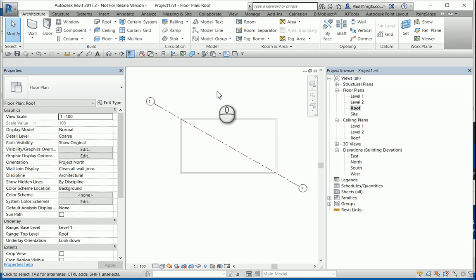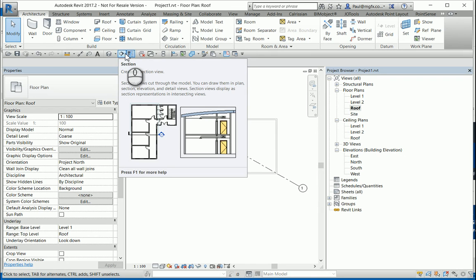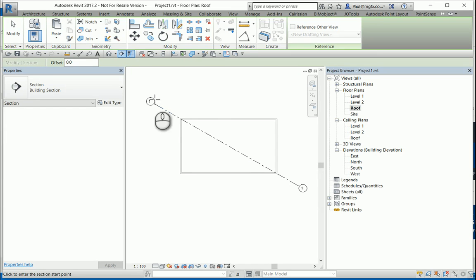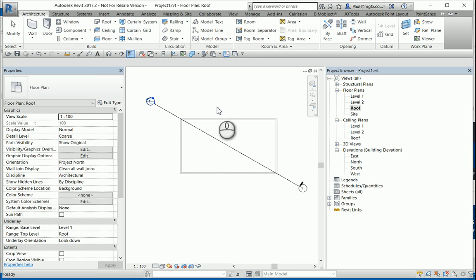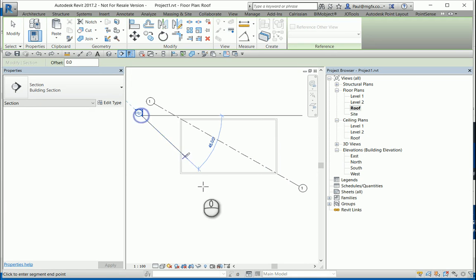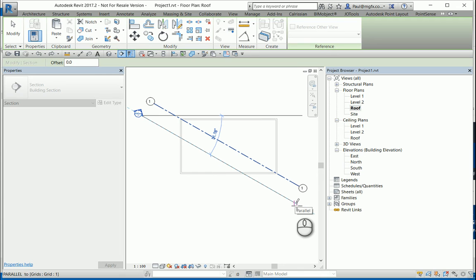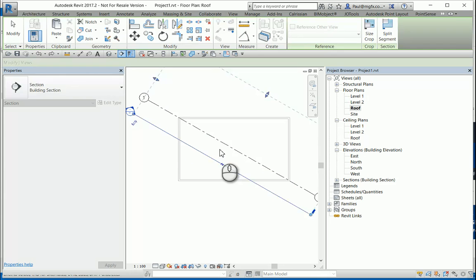Typically what one would need is a view that is normal to that plane, and you'd have to use this if you're using Revit LT. Using full Revit, we're going to use a different tool, but notice how you can either create that right on top of the grid line, in which case you know that it's going to be parallel, looking normal onto that plane, or otherwise I'm doing that. You will see how the section tends to highlight the grid line when it is parallel to it. Turns blue. Then you also know that that is normal.